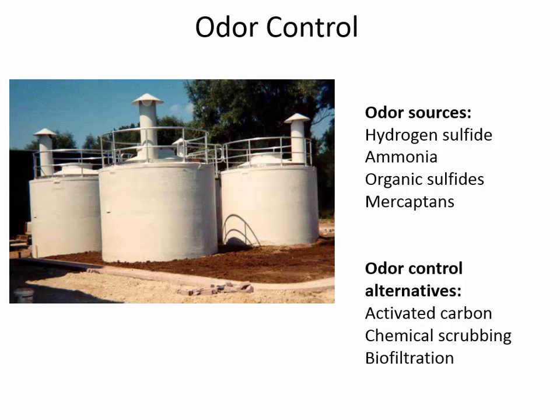It's a pretty unpleasant smell as well. So in the picture you can see that they've put a lid on the top of the trickling filter. And so inside the trickling filter, that arm is still rotating and wetting. We don't get to see it though because they put a roof and a lid, and inside that headspace above the filter is an activated carbon that is absorbing the odors. It's sort of like a gas mask, a reverse gas mask though.